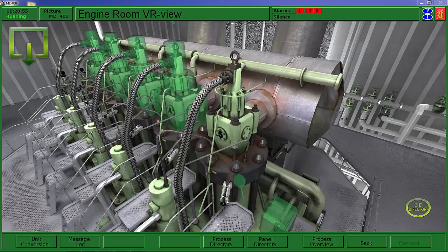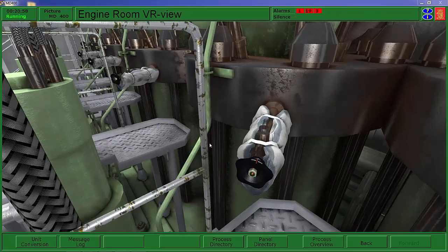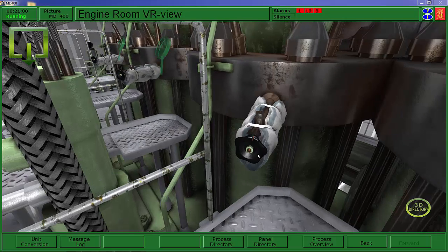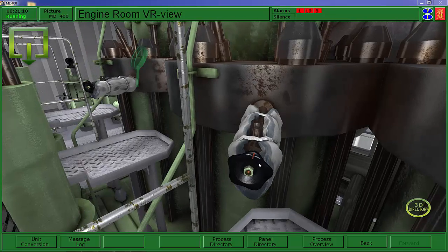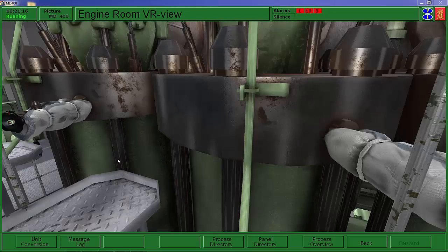We're going to go ahead and we'll open these up. And again, think of the opening here in the indicator cock compared to the cylinder. You wouldn't want to run this over on air with water in the cylinder because this is so small, it's a limited amount of protection that it could afford you.